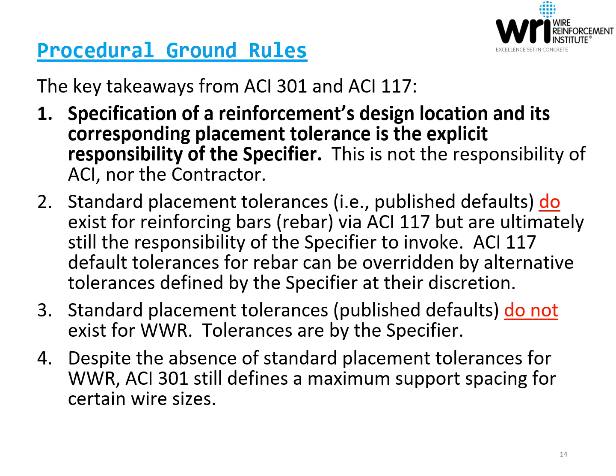Third, standard placement tolerances do not exist for welded wire reinforcement. Welded wire reinforcement tolerances are set by the specifier. And last, despite the absence of standard placement tolerances for welded wire reinforcement, ACI 301 still defines a maximum support spacing for certain wire sizes.